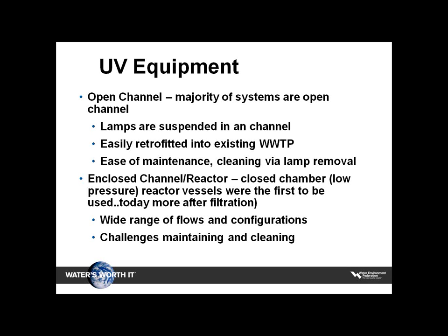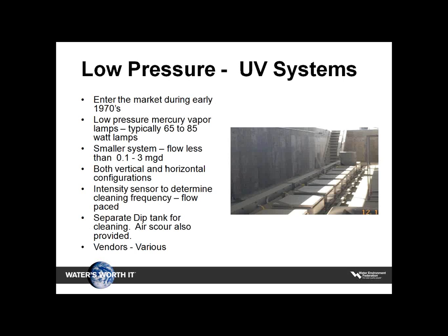Now, it should be noted that enclosed reactors were actually the first application of UV for low-dose applications, and some of those systems had problems, which provided some interesting challenges. But there are a wide range of flows and configurations that can be applied to enclosed reactors. There can be some challenges in maintaining and cleaning that equipment. In the past, most of those now have automatic cleaning systems, so it makes it a lot easier to use.